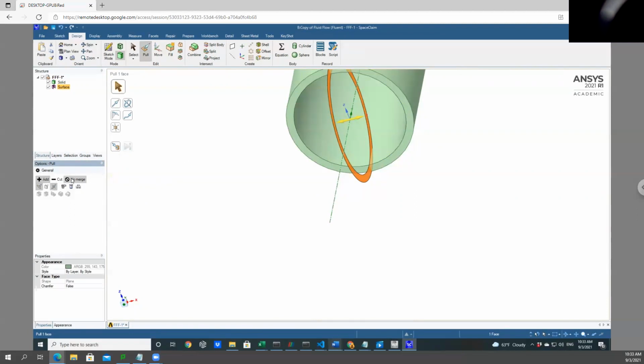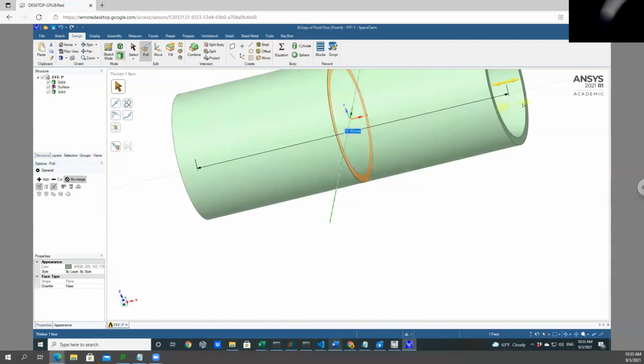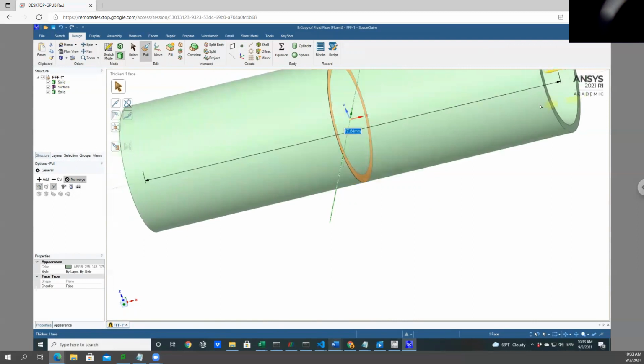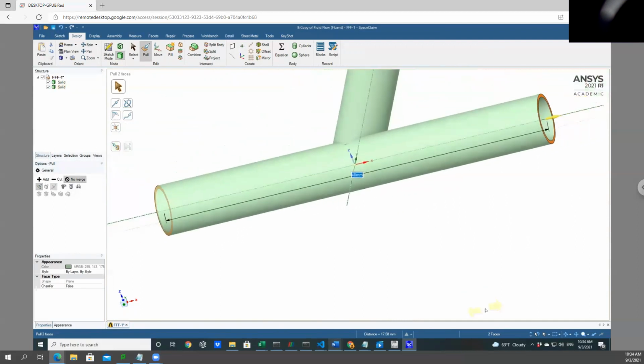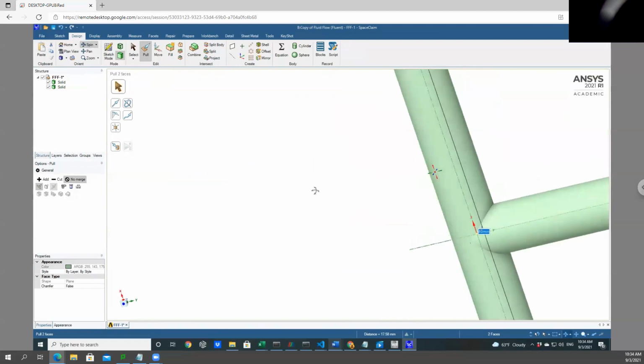Right. So no merge, and then drag and see. Now SpaceClaim is doing our horizontal vessels. So what we can do here is just put a random length for now of, let's see, 40, and do enter. So now go to sketch, go to design, click on the spin, and see, now we have